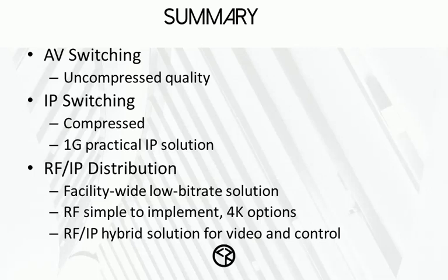For our company, we look at RF and IP as one universal system. The codecs are the same, so our encoders can distribute the channels as a QAM channel for RF distribution or as an IPTV channel for network distribution. And we do have sites that are using both pathways, RF to handle the major load and IP to take the signal to rooms and areas that do not have an RF connection.